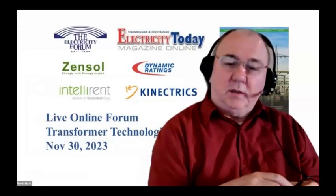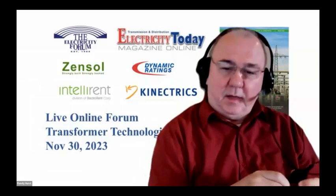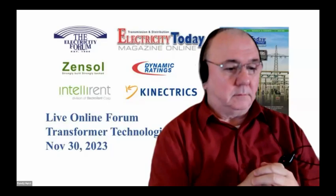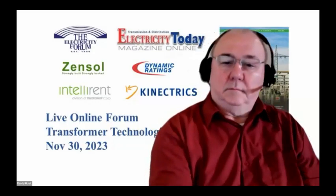The first question is, what are the common failures of the SF6 circuit breakers? Obviously, your most common is going to be gas problems. With modern SF6 breakers, that's by and large what we're going to see more than anything. Leaks, lockouts, cold temperature lockout are going to be first and foremost of our problems.